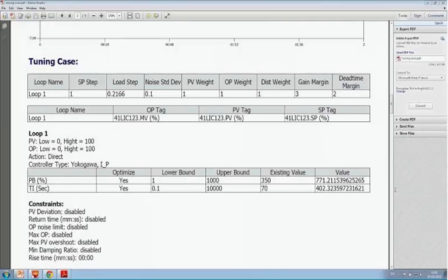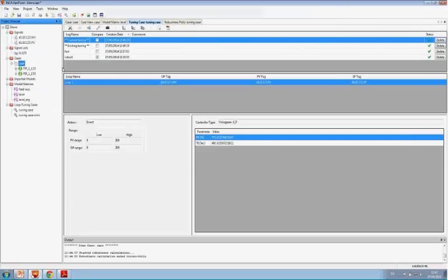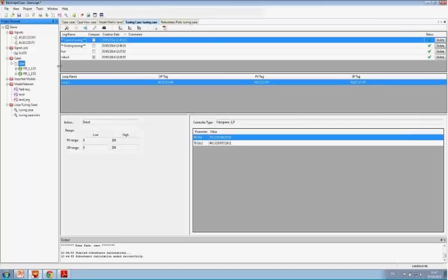Back to techniques. The word closed loop pops up here in the chat box. As said before, I've used open loop data to make the modeling, and you have to do that in AptiTune. We find that using open loop data will get you much better modeling than using closed loop, and it's not possible in that sense to use closed loop data to make a model. So it's very important to remember that you have to do an open loop test.